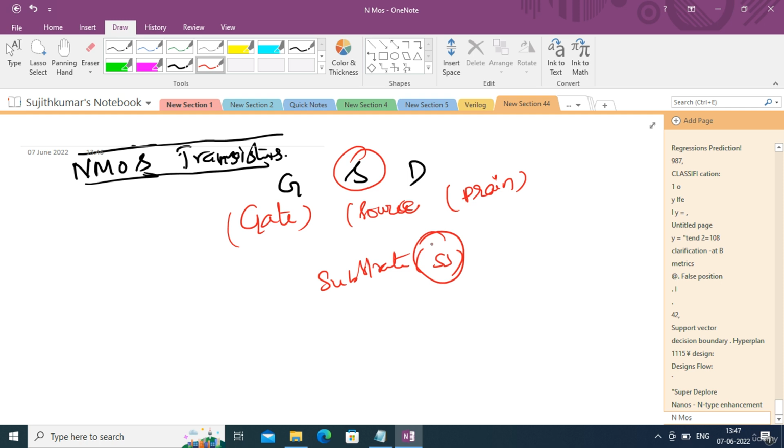Physically we are having four terminals, guys. Always substrate will be connected to either ground or VDD. Okay, so substrate will be connected to either ground or VDD. VDD means power supply, 5 volt. Okay, either 5 volt or ground. Okay, so substrate will never become another terminal. Okay, it is just again a physical terminal which will be either grounded or which will be pulled up, right?